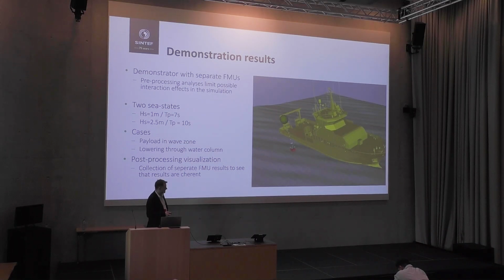And then we also simulated for some hours to lower the payload through the water column. That allowed us to look at how it would work with getting current and wind values as the payload descended, both in position, so the current would vary over the water column, and also in time.